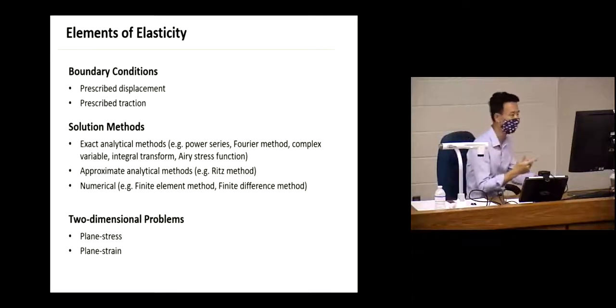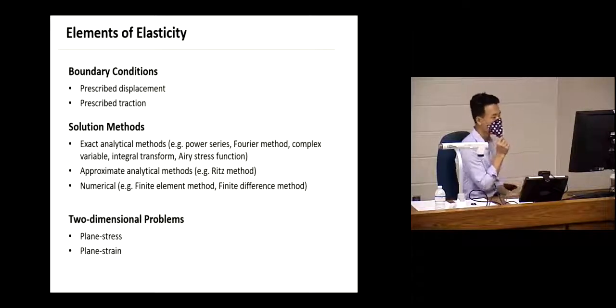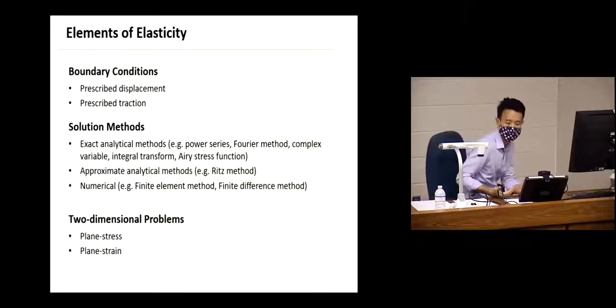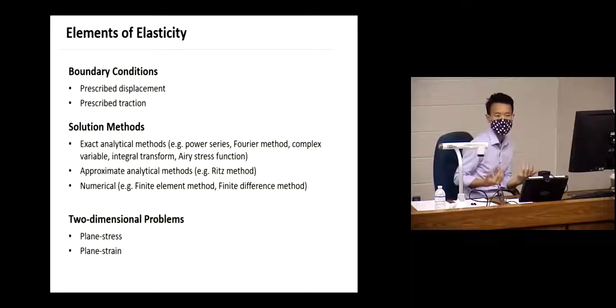Now this is where I want to talk a bit more about numerical methods for solving elasticity problems. We use the finite element method most of the time in solid mechanics. Right? There are other methods like the finite difference method. That is more common and popular in fluid mechanics. So the difference between these two is how you discretize the set of equations. In the finite difference method, because you are dealing with differential equations, you can directly numerically discretize the equations, right? That's the finite difference method.